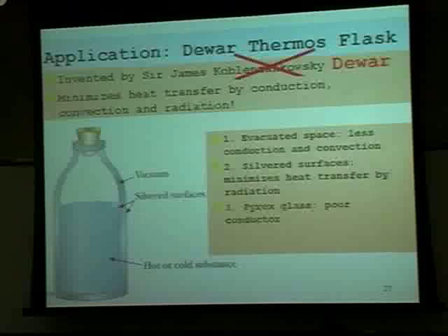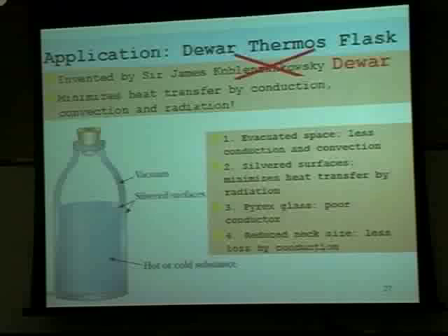Pyrex glass, a poor conductor, not allowing conduction transfer. Reduced neck size, again, reducing the amount of transfer by conduction and or convection through the neck itself. Very good design. Keeps your substance either hot or cold.